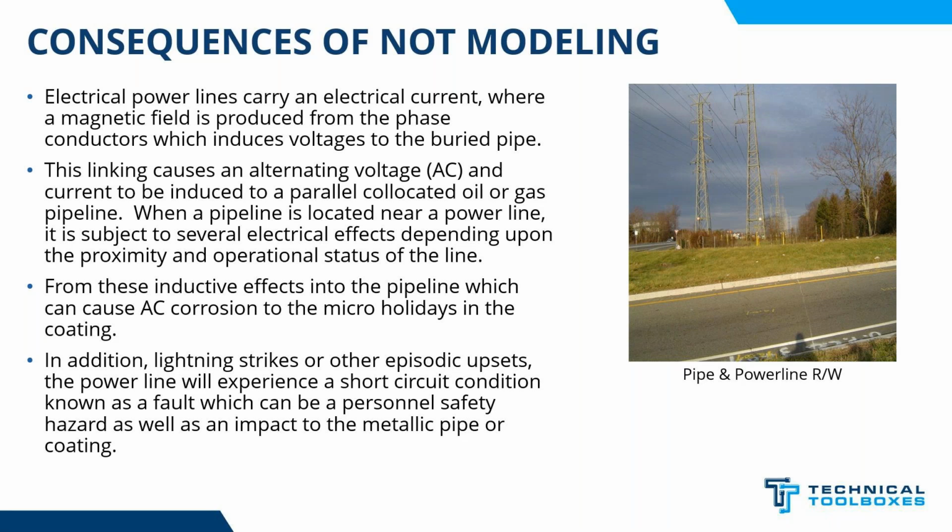And then also we need to think about lightning strikes. Where am I located? Are you in a high lightning strike area? What effects will it have? And so on and so forth. What kind of episodic upsets occur? Like in this area right here, we had 5 substations within 15 miles. And you know what the big problem was? The power company didn't know when they were going to turn them on, and which ones were going to be used. Why? Because they had industrial loads at night that they couldn't run in the day up in this area. They ran the commercial and the residential in the day and industrial loads at night.